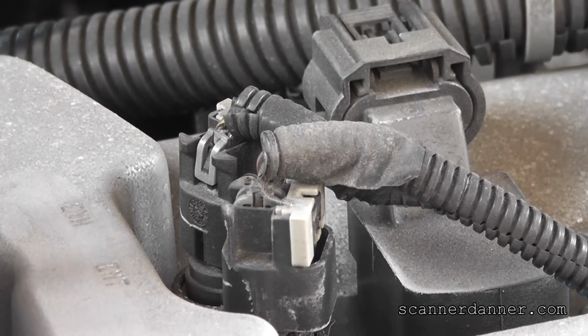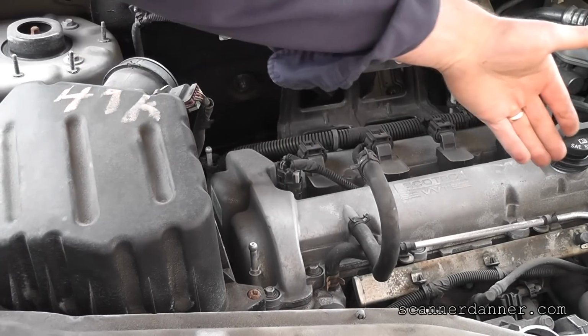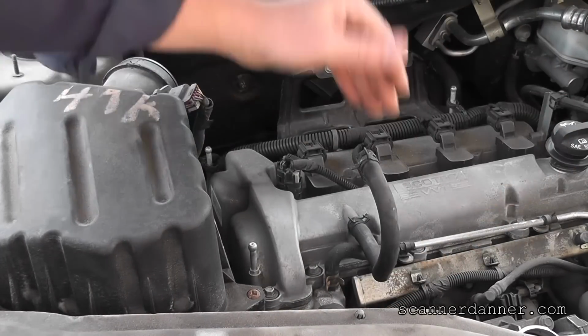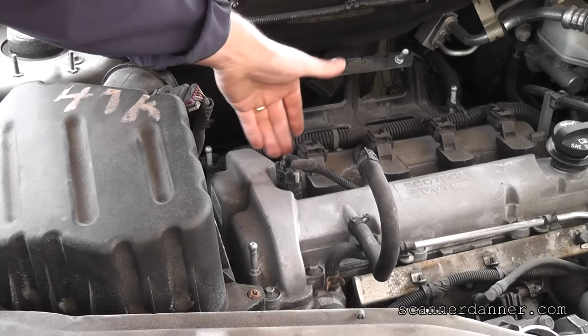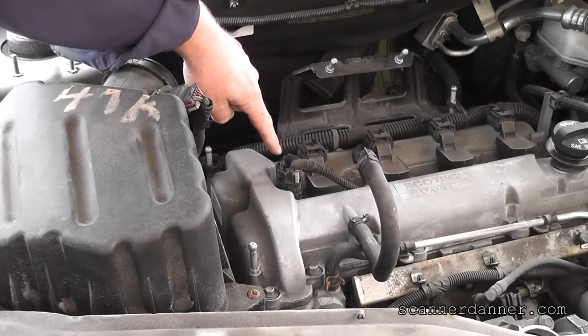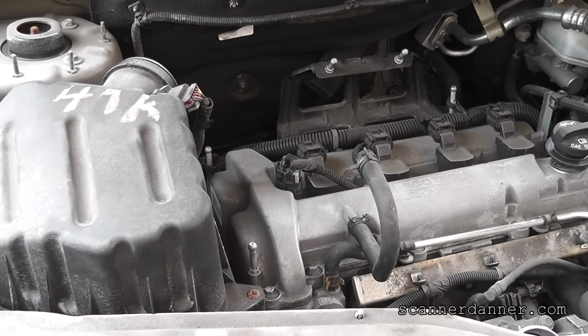Now, of course, a little bit of thinking here too. The front is where the intake manifold is. Another method obviously would be, this is the intake cam as noted by the intake manifold sitting right here and the exhaust manifold back here. This is your exhaust cam, but it's nice, it's stamped on there. Our focus is going to be on this one right here. We're not going to check this like the flow chart told us to. We're just going to do some voltage measurements. I have a scan tool that I can bi-directionally control it. We'll see what we got.